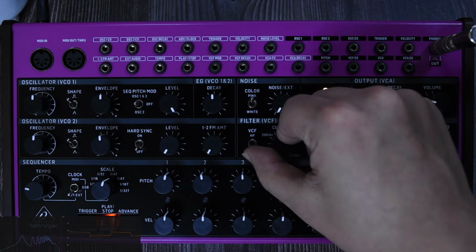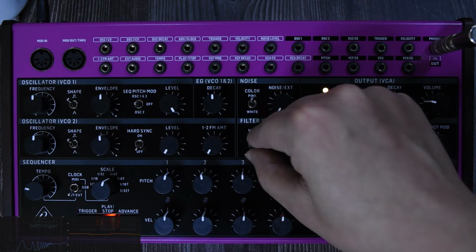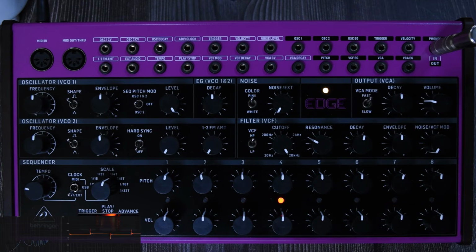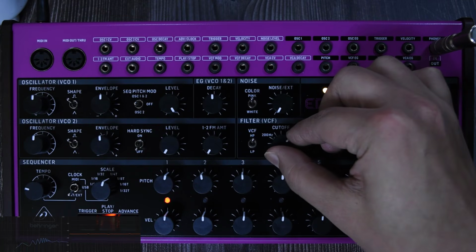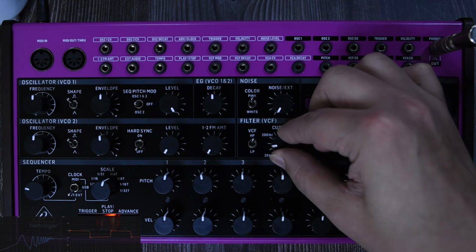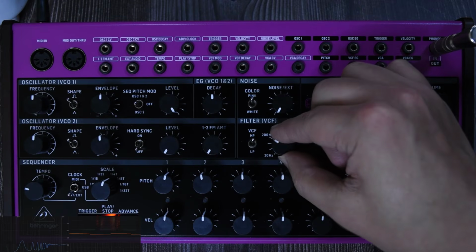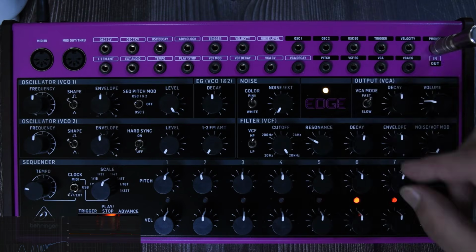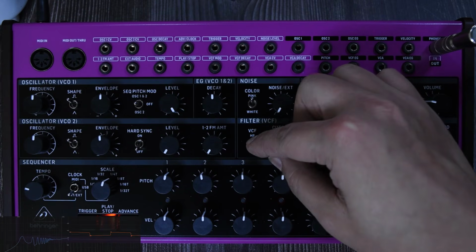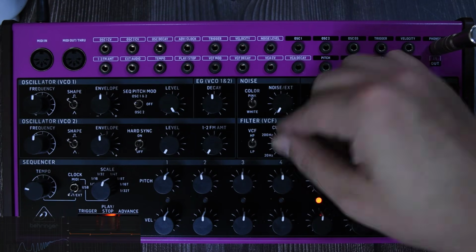Now, the other thing is going to be a high pass. If I go to high pass, we are doing the opposite. Instead of chopping highs, we chop lows. And right now, if we see the spectrum, the lows are just lower. If I go the other way, we're going to see and hear the change. Now we are doing pretty much nothing. So as I keep going up, right here, we get less lows and more highs. Completely different to the low pass.